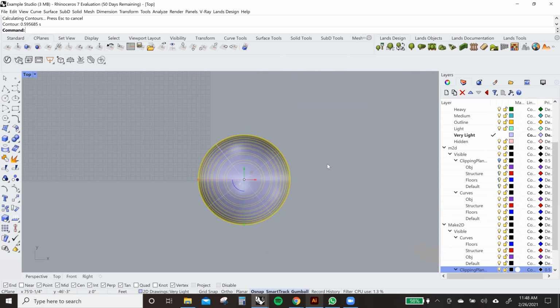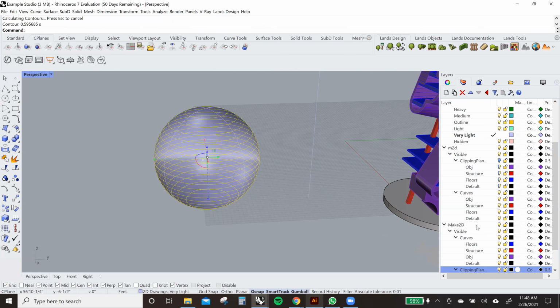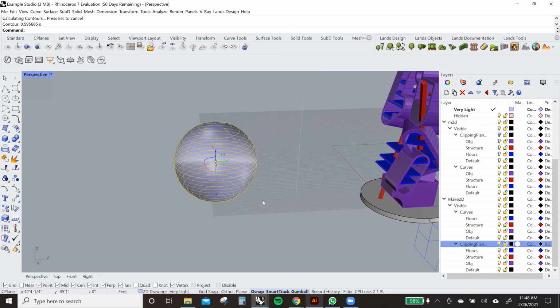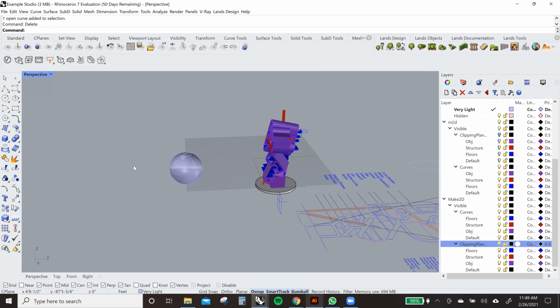And I would advocate for making all your contour lines on their own layer. Yeah. They'll come in on their own make 2D layer, and you can make them even lighter or the same lightness as your furniture, because they're not real, right? They're just describing a curved surface. Yeah. And you can do that if you have a section. We can contour in the direction the section is looking at, in order to make those things substantially more visible.